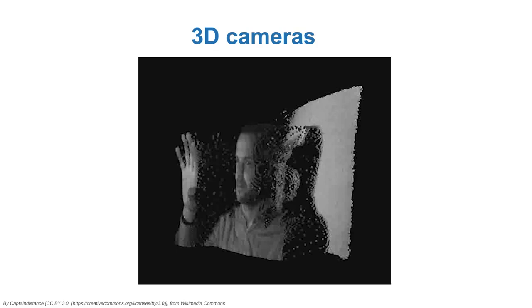Finally, I would like to mention a different type of camera. A camera that can provide the distance directly for each pixel. That is, the color and intensity of each pixel is then proportional to the distance. What makes this possible is what can be seen as a combination of near-infrared night vision systems and LiDAR. By illuminating the scene with a projector of near-infrared light, similar to the near-infrared camera solution, but with short pulses of IR light of known duration, the time of flight of the IR light can be measured in each pixel of the CMOS sensor.